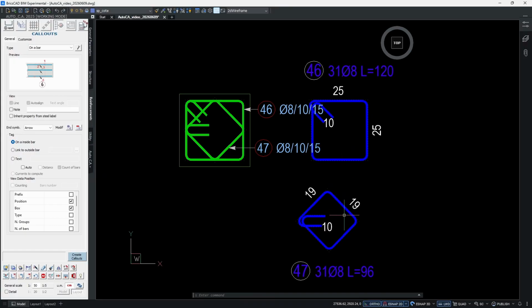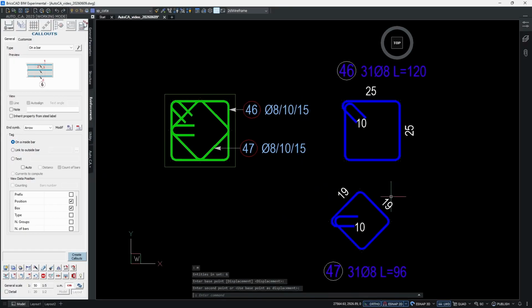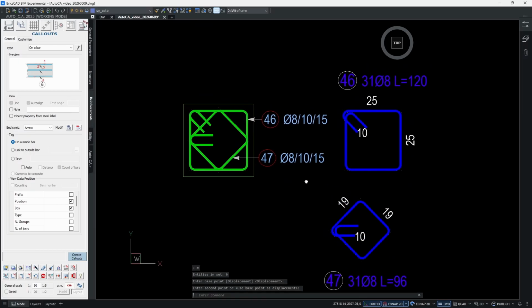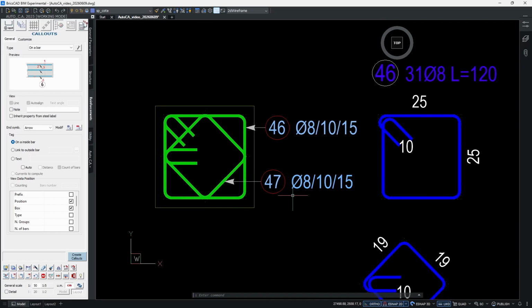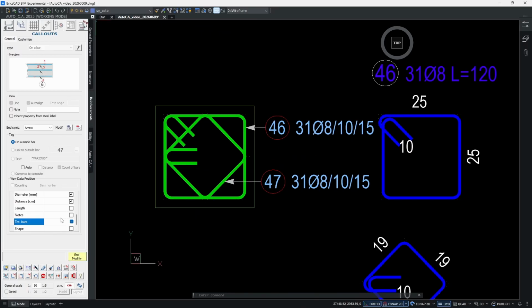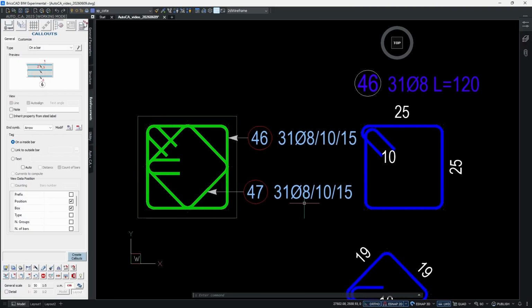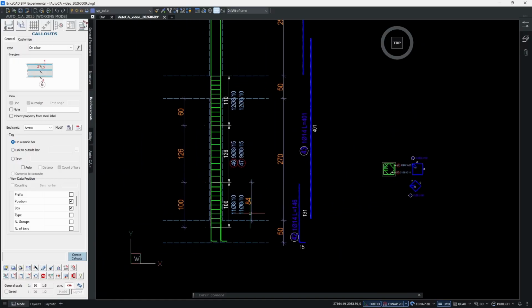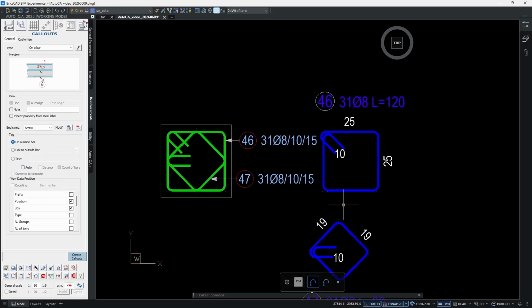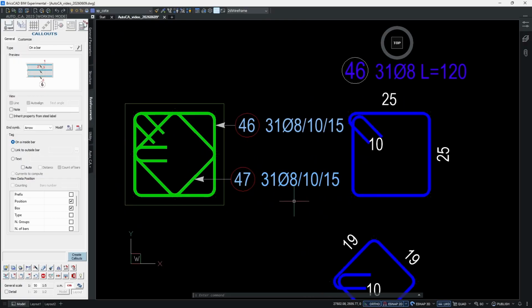Now let's check back onto our cross section. I'm gonna relocate outside stirrups because our callouts got bigger. We have now the distribution distances 10 and 15 displayed here, but we can further modify these callouts and add the total bar of the series, the total bar count. So now we know that in this floor, for our column, we need 31 stirrups.